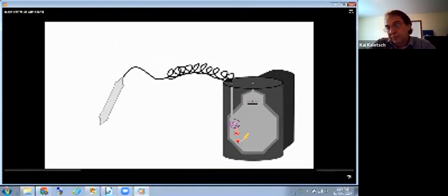Some mitigators have found success while sampling each hole for 90 seconds and then going on to the next one. The 90 seconds is a good number. It is enough time to get a few air changes in the cell and for the readings to stabilize without bringing up a lot of radon decay products.